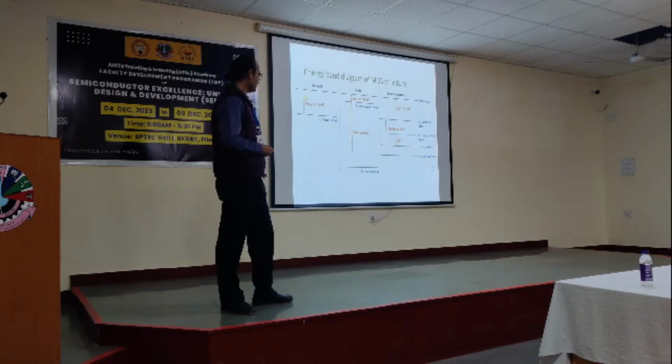Yes, so what I want to say is if the metal work function is up to here, then up to this line, electrons will get shifted towards the semiconductor, silicon in this case, and there will be depletion. If you go below this point, what will happen? Reverse will happen. There will be accumulation then. Electrons will come towards the metal, right?